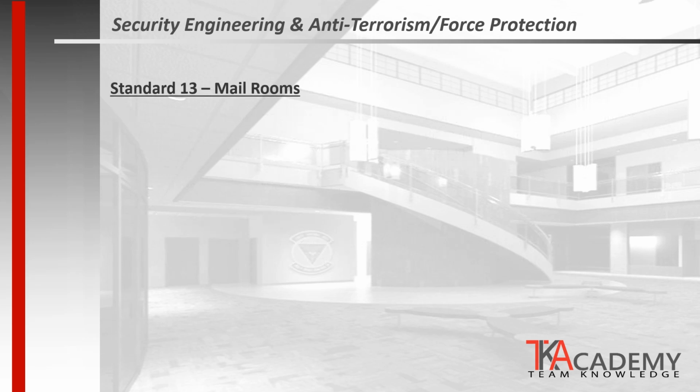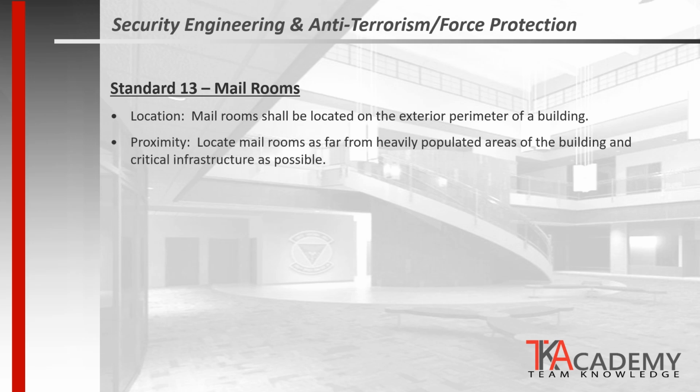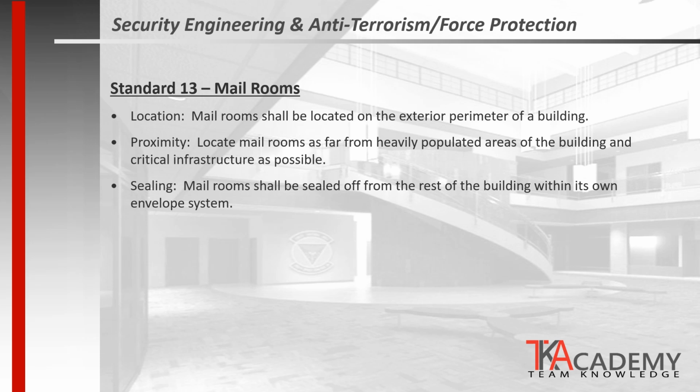Standard 13 looks to mitigate the threats of an explosive or hazardous material being delivered through the mail system. Mailrooms are to be located at the exterior perimeter of a building and should have their own dedicated building entrance. They should be located as far from heavily populated areas of the building and critical infrastructure as possible. Mailrooms are to be sealed off from the rest of the building and have their own envelope system.